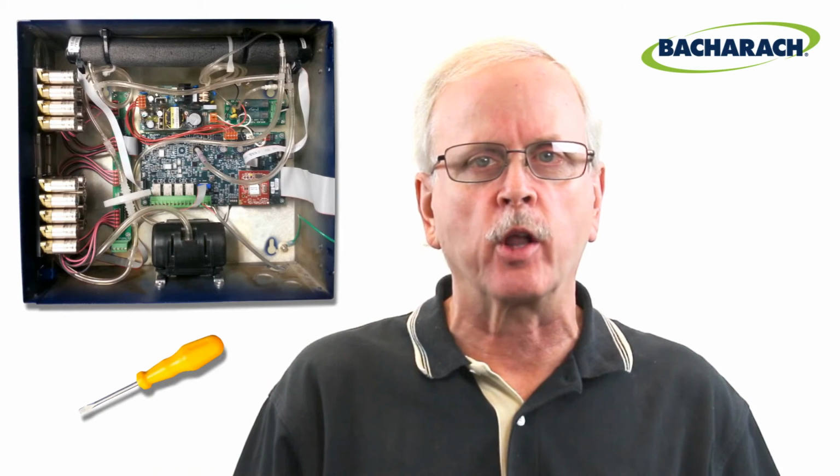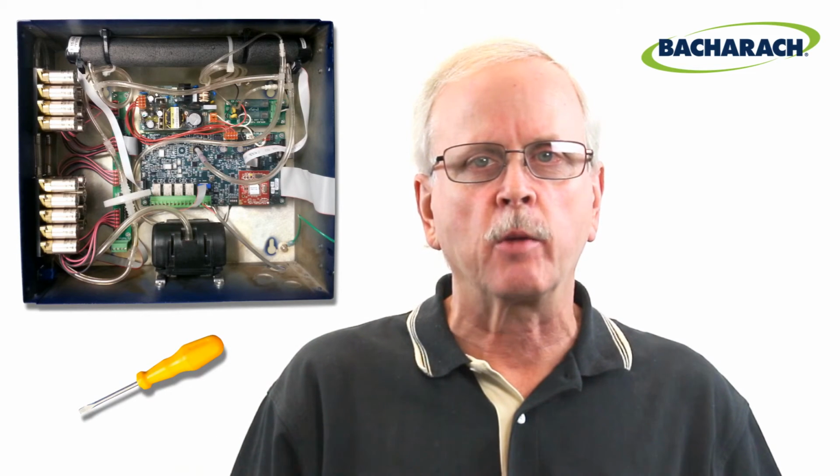Not everyone has a magnetic field detector handy, so here's an easy way to check for an energized solenoid on a multi-zone. Lightly hold a small screwdriver or paperclip above the suspect solenoid and move it back and forth very lightly. If the solenoid is being properly energized by the solenoid PCB, you should feel a slight resistance as you move the screwdriver or paperclip back and forth through the magnetic field.